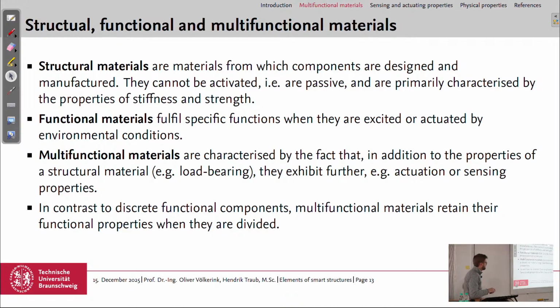And again, in contrast to functional components or functional elements, these multifunctional materials retain their functional properties when they are divided. If you cut a mechatronic actuator in half, then it won't work anymore, and the piezo ceramic would still have its properties even if it's cut in half, for example.